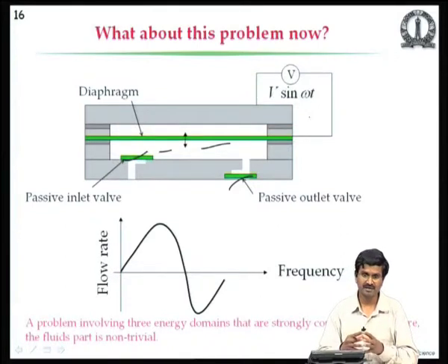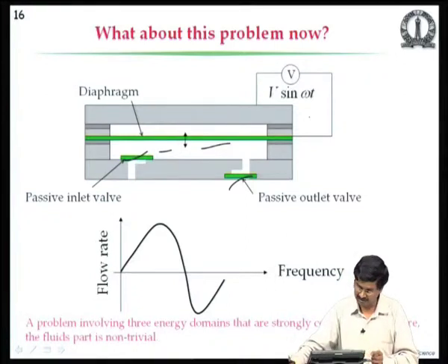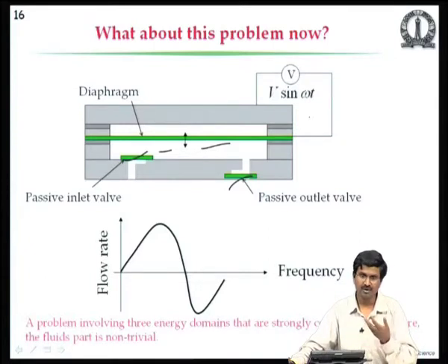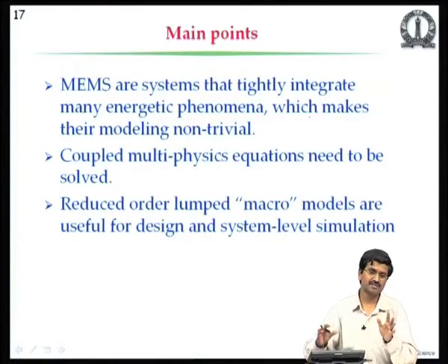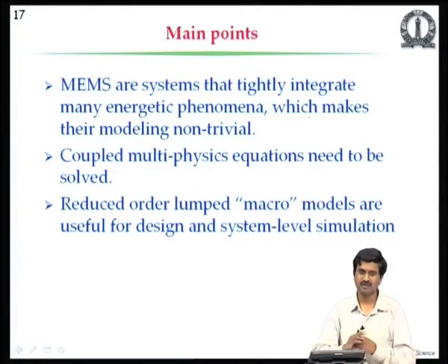What we have not done in detail is the fluidic effects. So, you have to read about Navier-Stokes equations and the special conditions as to when they can be simplified to Couette flow or Poiseuille flow or squeeze film isothermal Reynolds flow, and then use the appropriate simplification to solve the problems, or go to the differential equation and solve the complete numerical solution.